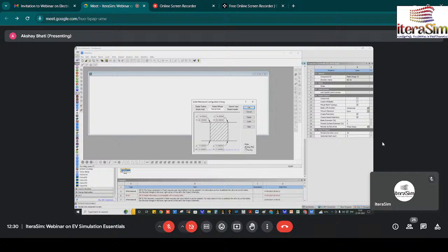And here, if you talk about angle and thickness, after that you can give the angle. Let's say I am giving a variation of angle from leading edge to trailing edge of 45 degrees, and at the leading edge I am taking a 2 mm radius. You can also decide the thickness depending on the fan blade material. Mostly, if the blade material has lesser stiffness or lesser strength, you have to design a thicker fan so that it can be structurally stable.